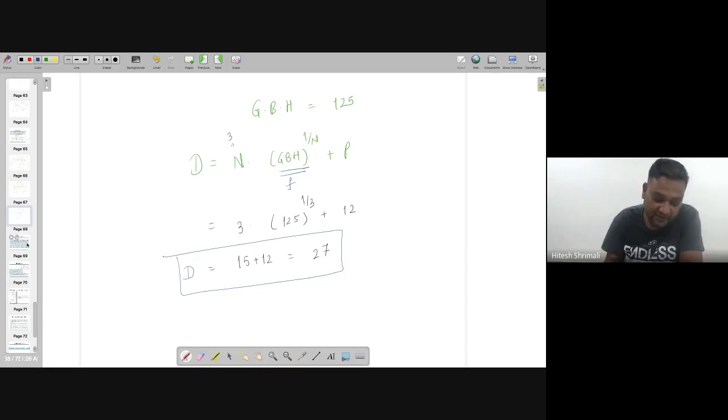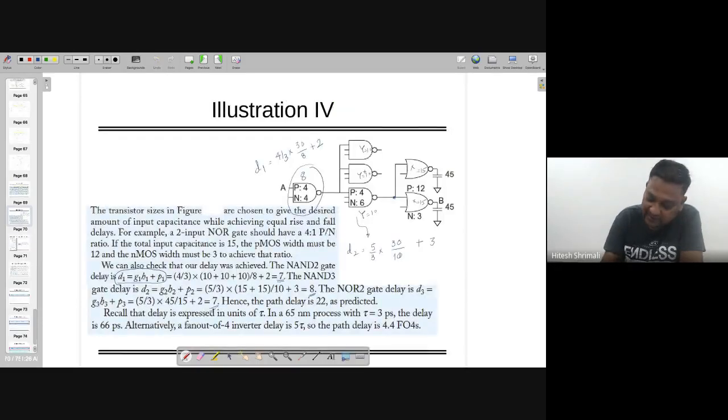But notably, in this particular technique, you should know what the input capacitance is at each node. If you don't know what y and x are, you cannot have the final answer, because each stage needs the electrical effort. So that should be known to you. Notably, we also do not have an idea what f is without calculating the whole thing.